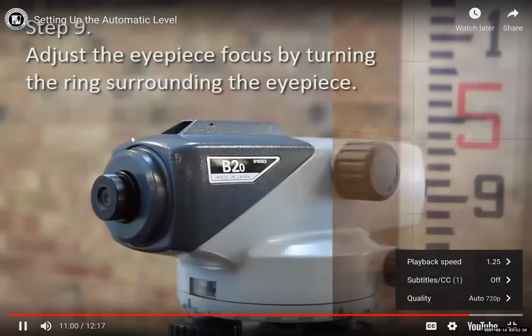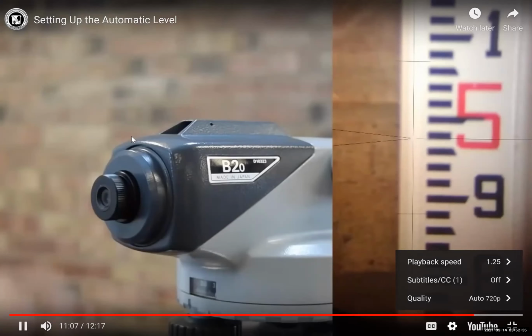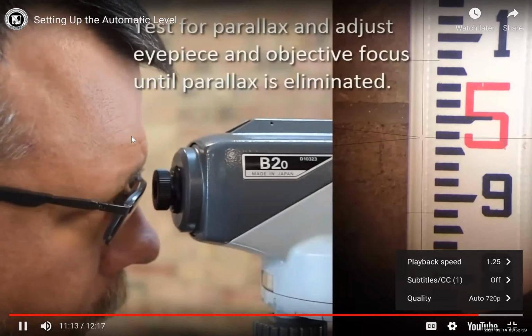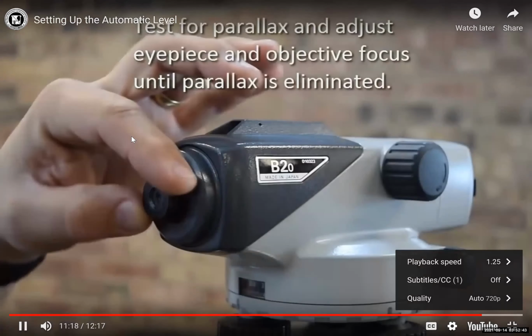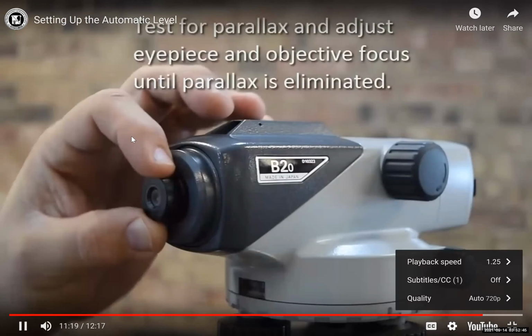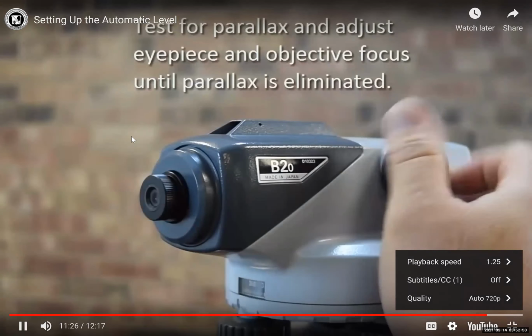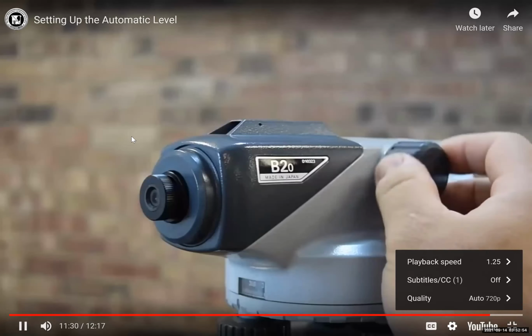Now, it's time to test your focusing results for parallax. Parallax exists when the crosshair appears to move up and down as you move your head. If you detect parallax, refocus the crosshair to its sharpest and darkest condition, and then adjust the objective focus as needed. A few fine adjustments usually get rid of parallax.